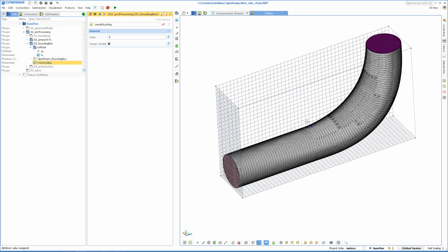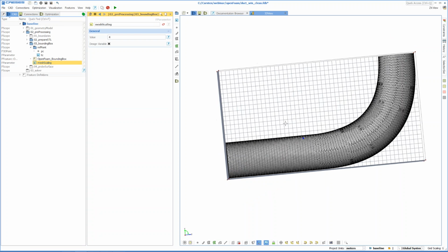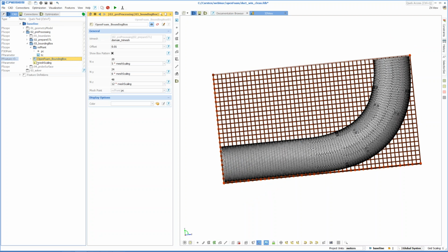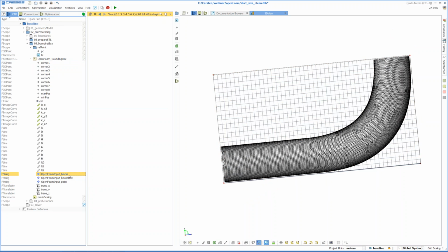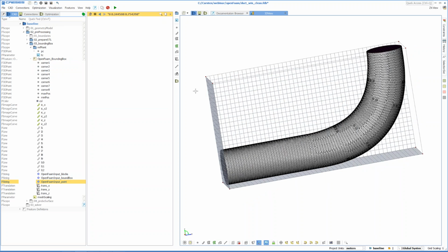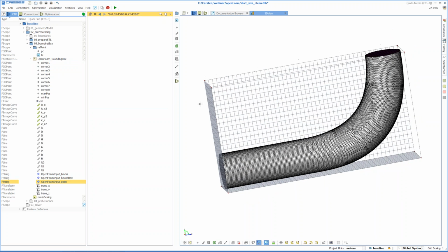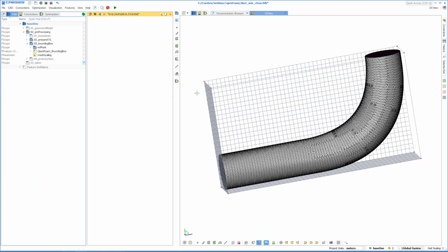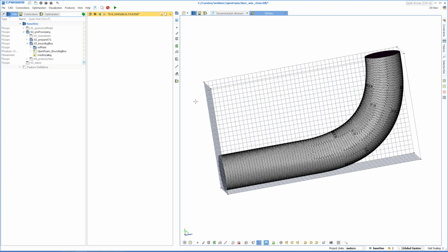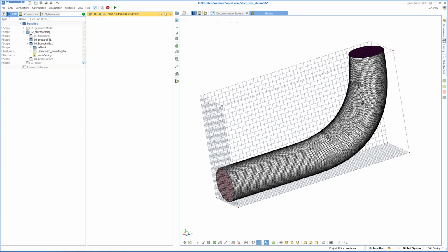So this is a really nice thing. And the output of this feature is basically these two strings here at the bottom. It basically creates a string for my bounding box, for my blocks, and for my reference point. And I will use these strings later in my OpenFOAM dictionaries. So that's basically it for the preparation of the geometry and the bounding box.